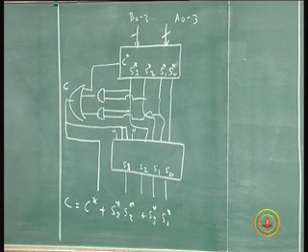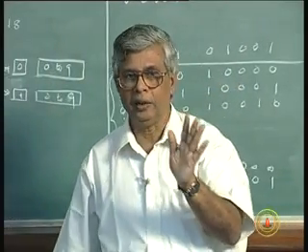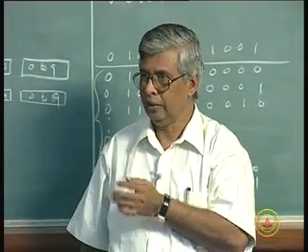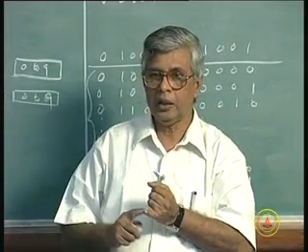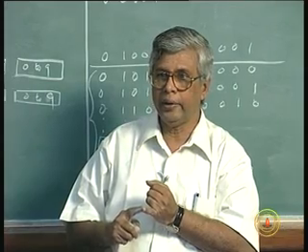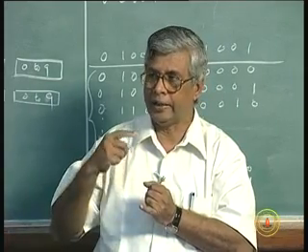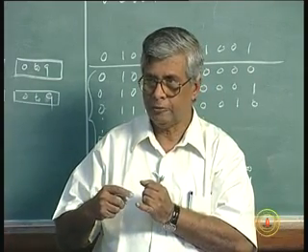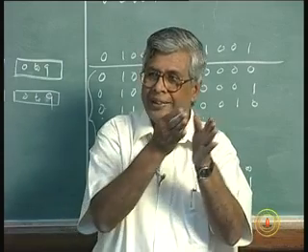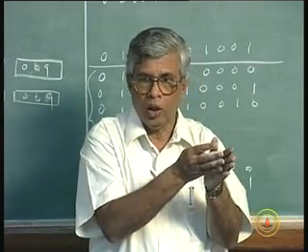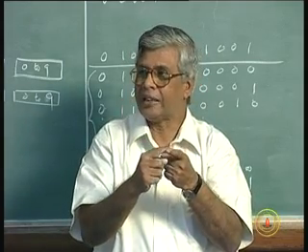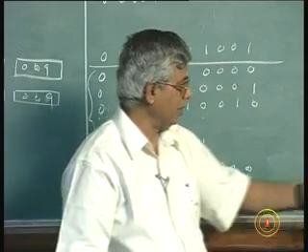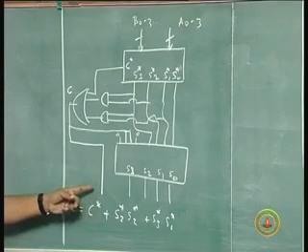I have to add 6 to the sum when the sum exceeds 9. As soon as the sum exceeds 9, I have to have a carry addition of 6, which means I already get into my second digit. So, whenever I add 6, I also should get my extra digit. This is that extra digit I was talking about, which can be 0 or 1.